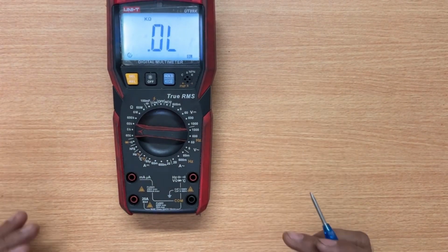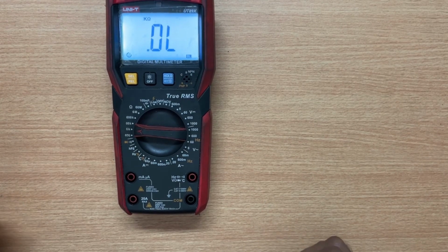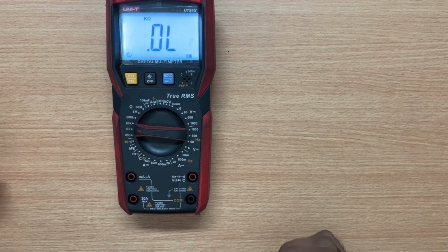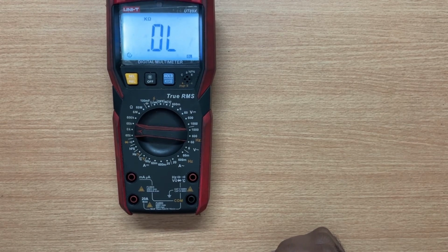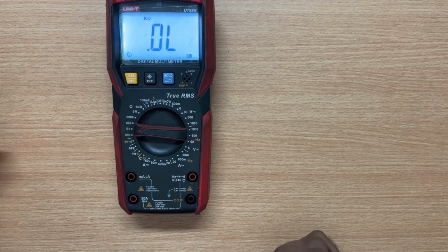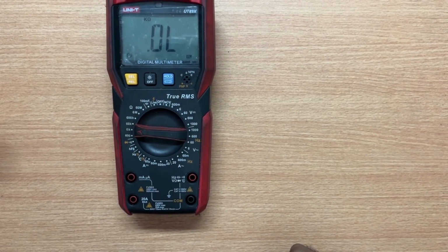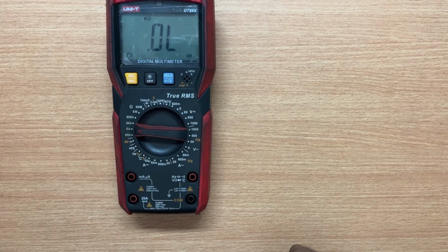The funda is clear that if you want to measure something which is ranging from 0 to 10, select a knob which is closer to 10 or more than 10, so that you will get the value of 10 exactly. Because if your range is going to 10 and you select 9, you will not get the accurate data. So your selector switch should be equal to that highest point or more than that.